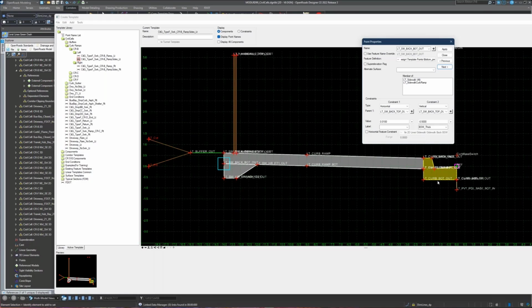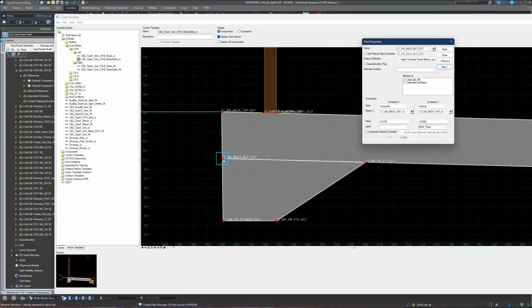But in a lot of the bottom mesh stuff, we've got a lot of vertical faces. What this is trying to do is, if you have vertical faces and try to create that bottom mesh, you run into a lot of issues because it will not create a mesh that has vertical faces. So all I'm doing is offsetting these points just a tiny bit, like horizontal 0.01, so this point is 0.01 from the point above it, so that this isn't a vertical face.